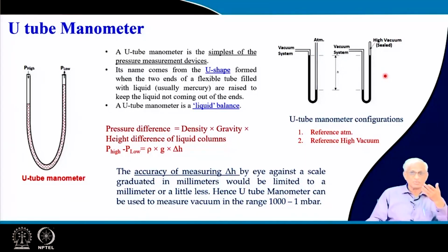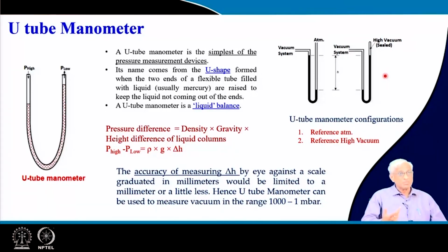If you take 10 to the power minus 7 as minus 5 and try to deposit a thin film and use it for an IR detector or for semiconducting device applications, it will not work properly, because it is impure. Minus 5 torr is much less clean compared to minus 7, and you thought it was minus 7 because your gauge is not proper.